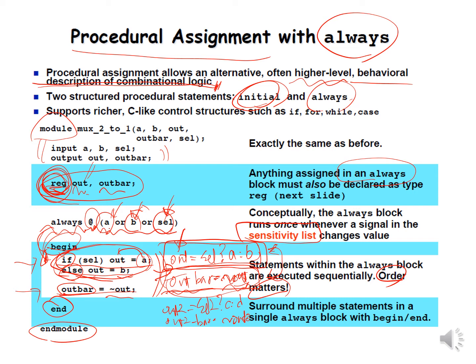You can define multiple actions. But one thing you should also remember is that even though the execution is done sequentially, the actual hardware is exactly the same as the previous continuous assignment. This behavior is interpreted like a conventional combinational logic. So this is how the tool interprets the variable and how it evaluates the provided statements.